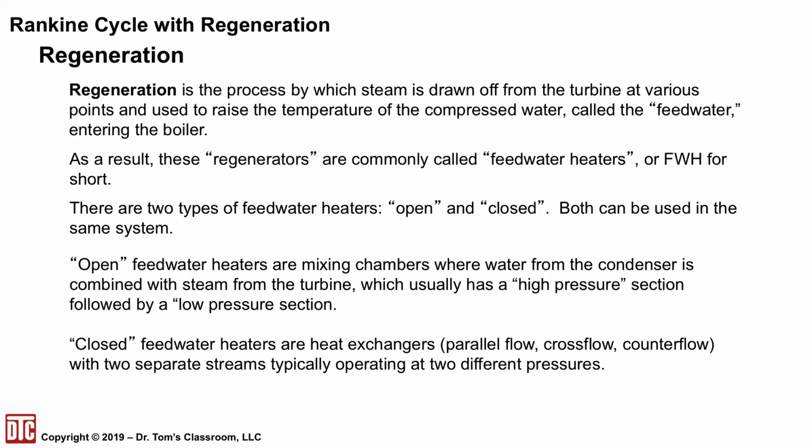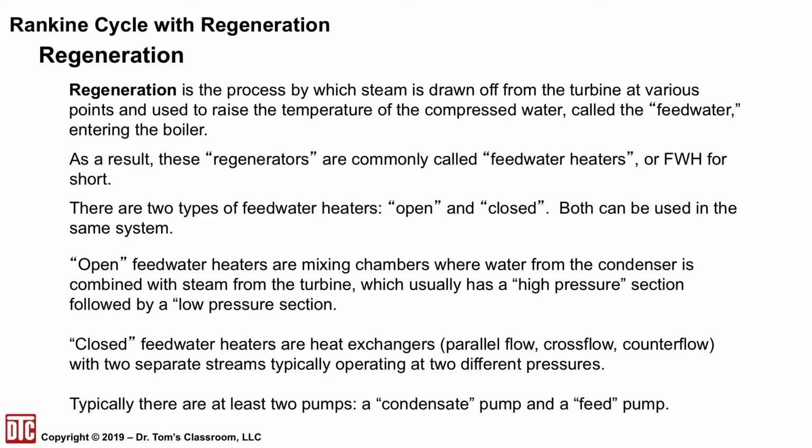Closed feed water heaters, in contrast, are basically heat exchangers, parallel, cross flow, counterflow, etc., where you really have two separate streams and they are usually at two different pressures. At a minimum, there are two pumps, a condensate pump and a feed pump, the feed pump being the main pump that we have already been looking at with the basic ideal Rankine cycle.